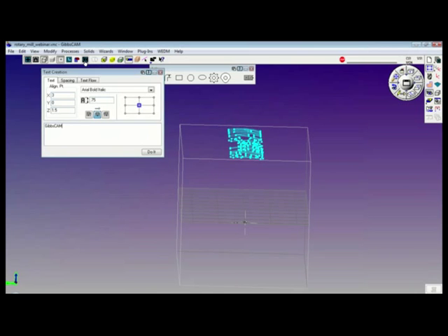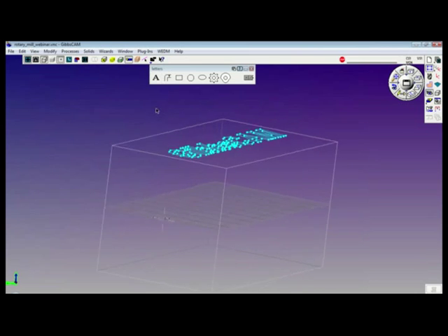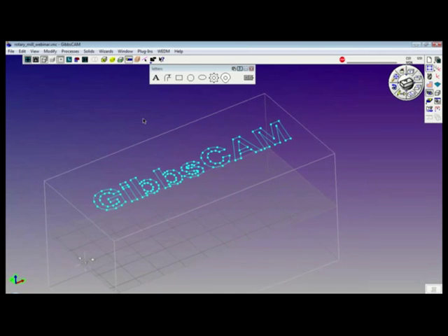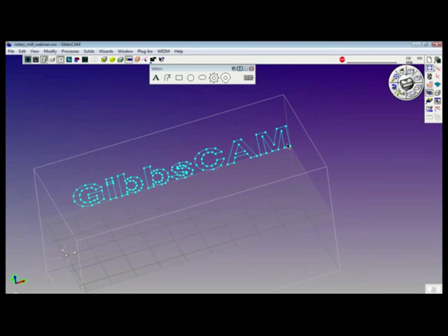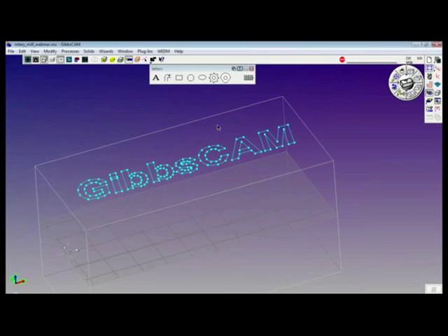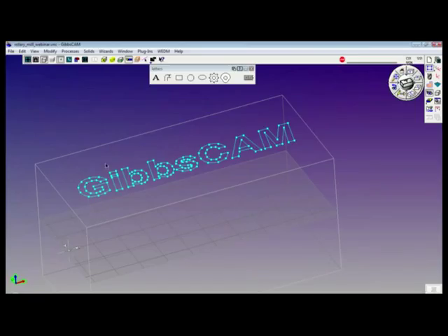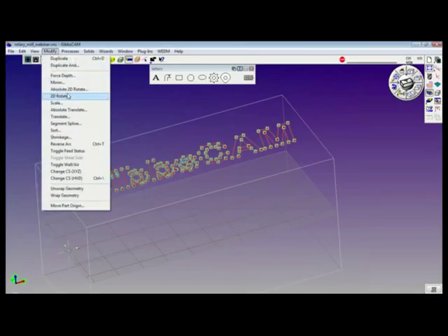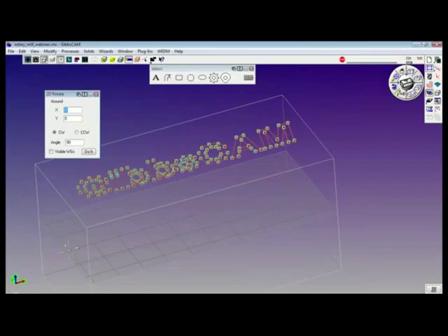It's in wrap mode, you can see. Now, that's straight along the cylinder. What I'd like to do is put it at an angle. So hold the Shift key, drag a window around the entire lettering. It'll all select, modify, 2D rotate around X3, Y0. In the counterclockwise direction, give me, let's try 30 degrees. See what that looks like.